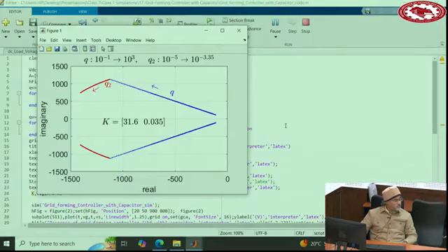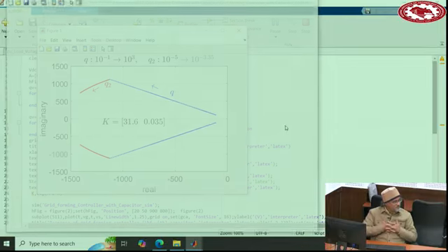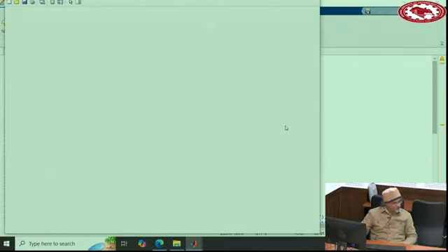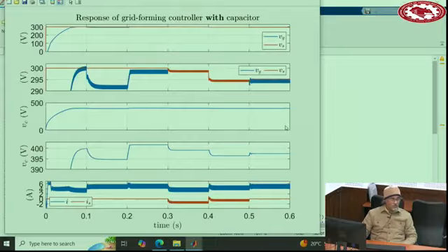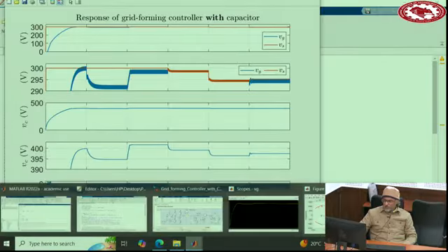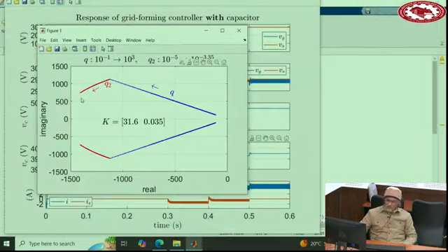So first it makes two matrices, properly selecting the pole location, and then it runs the simulation. LQR to get these gains K1, K2. Right, exactly. But first we need to select the pole position where we want to. What we do basically, we change them and roughly find a point that gives good damping and good speed.